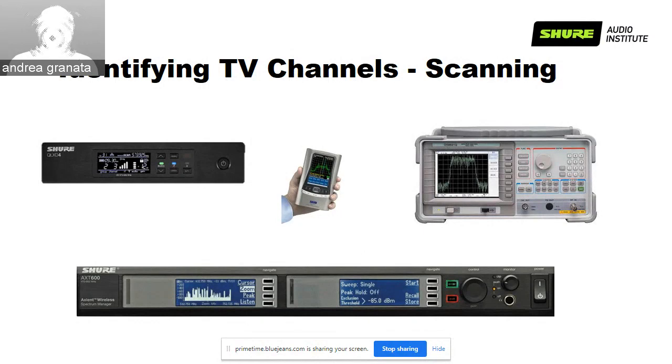We have different categories of scanning methods. One is the network receiver connected to software, most likely Wireless Workbench. If we are working with another brand of microphones, we can still do two things. We can use a different software, or we can convert the data taken from any manufacturer into a format that can be used in Wireless Workbench. Then we may have some handheld spectrum analyzers that, again, are not immediately compatible with all the software, but there are a lot of conversion tools around that can be used nowadays.